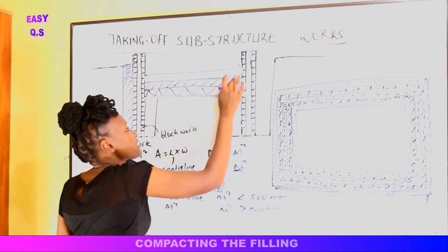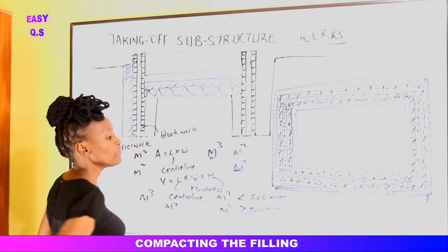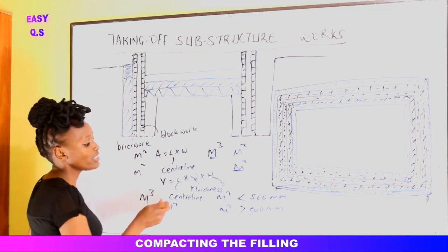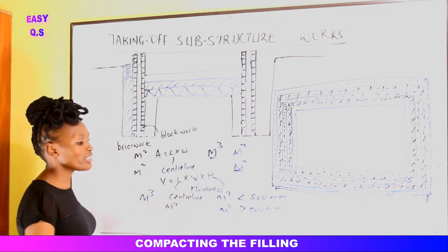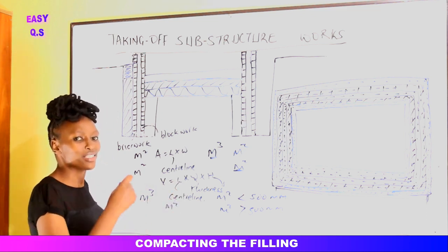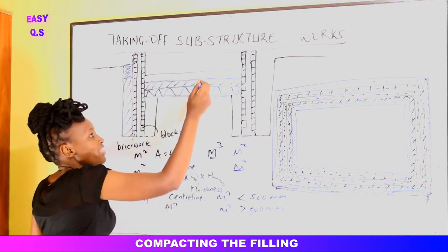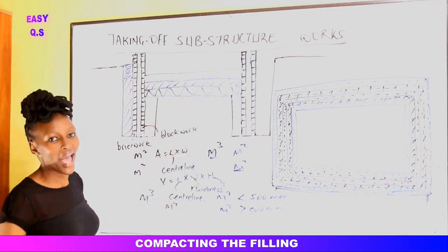If this is our concrete bed, we are told that we should measure it in terms of meter cubed. If it's measured in meters cubed, it is length times width times height. So the same area, length times width, inside the building, the same dimensions, internal dimensions of the house, length times width. Then we shall multiply by the thickness of the concrete as the height.